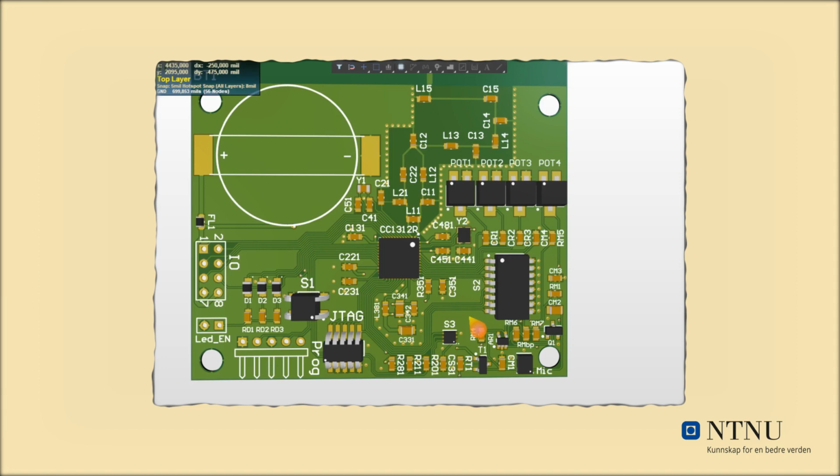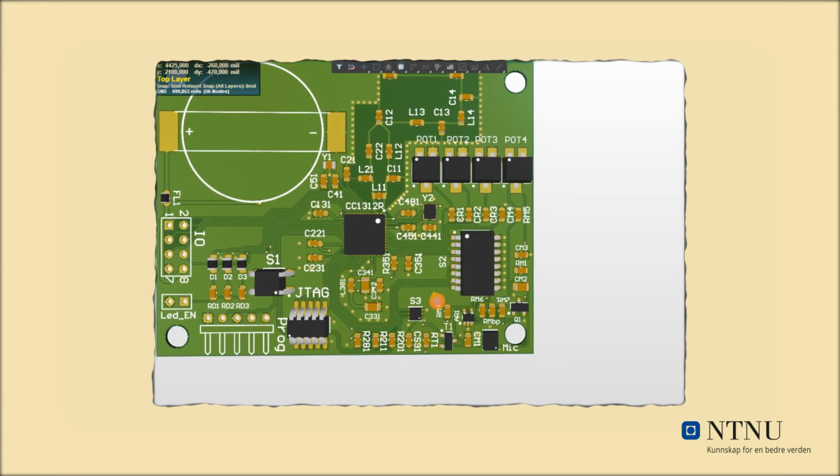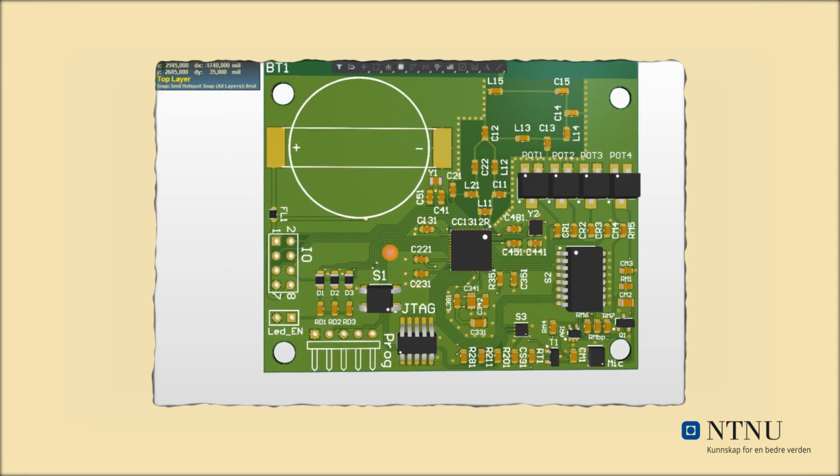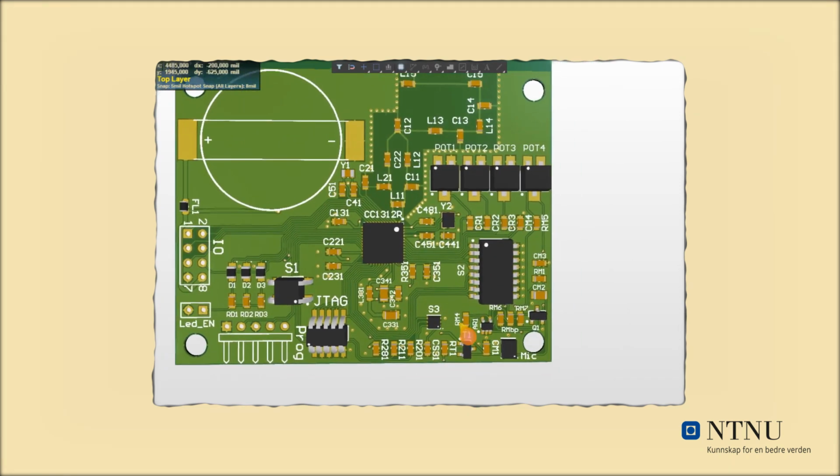It uses the I2C standard and has an interrupt pin, so we can make the MCU sleep while it's calibrating the value. It has 6 door switches here, which are general I/O pins, but we use them for the door switches. It also has 1 pin for VCC and 1 pin for ground.